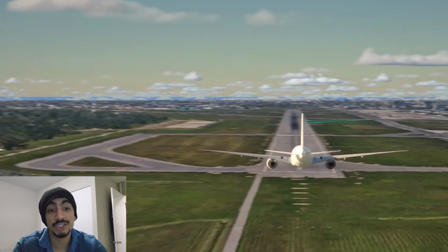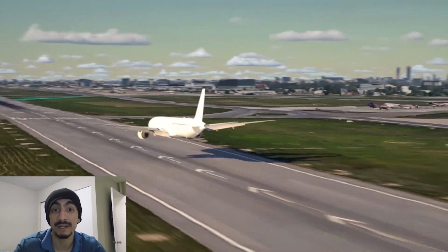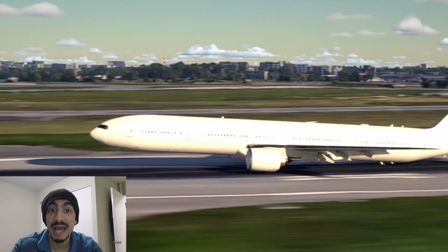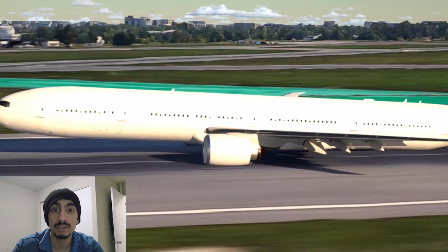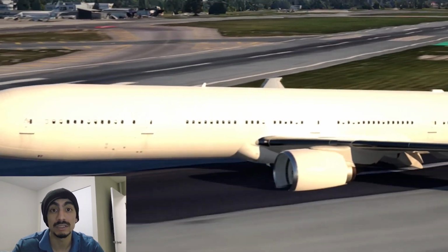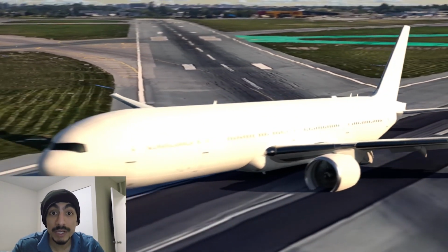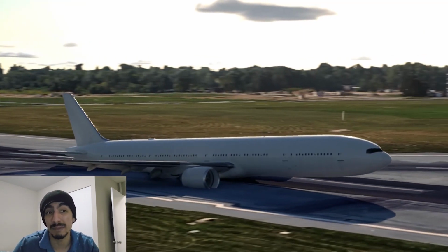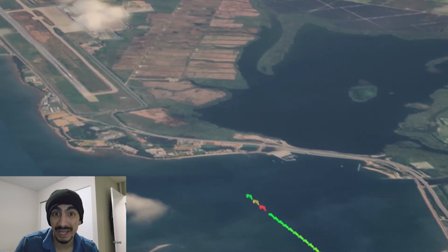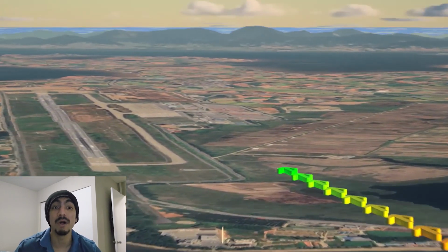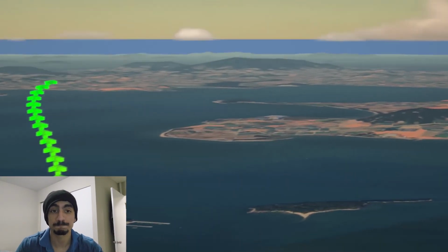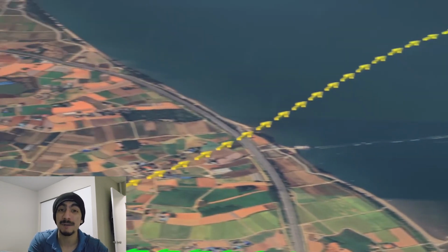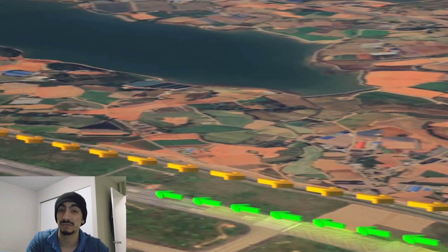And if the engine surges or flames out, then the pilots have only a few seconds to respond, like lowering their gear, adjusting flaps, deciding to go around. It's very, very hard. It's very, very difficult. And if debris from that damage severs a hydraulic line or cuts electrical cables in the aircraft, you're now dealing with a compound emergency where multiple systems are compromised all at once. At that point, even the best design and the best backup systems can be put under a ton of stress.